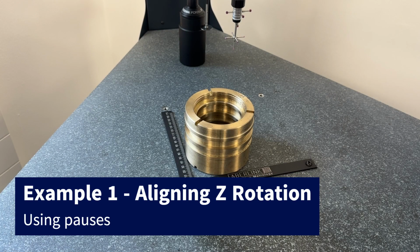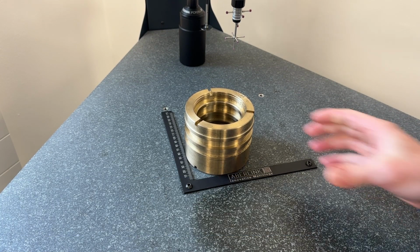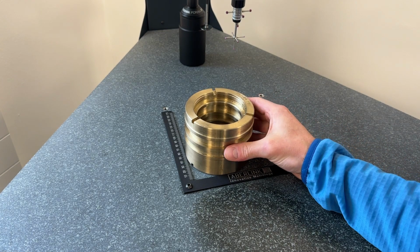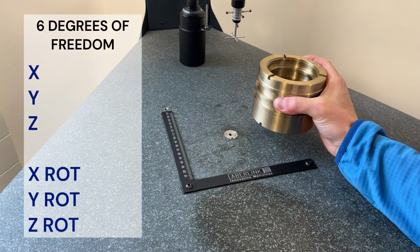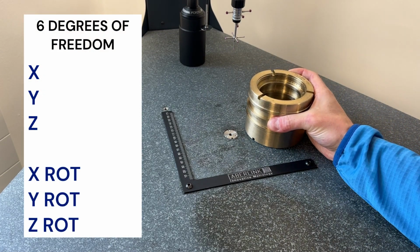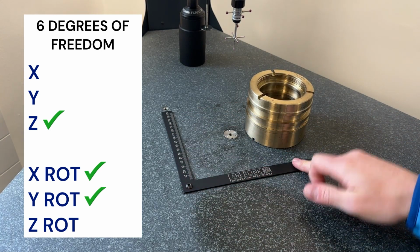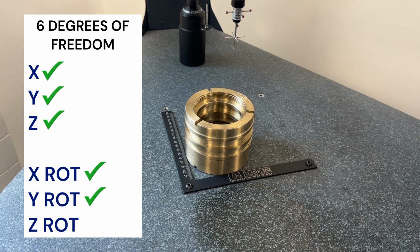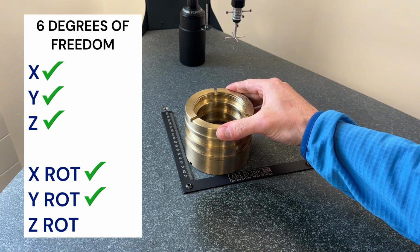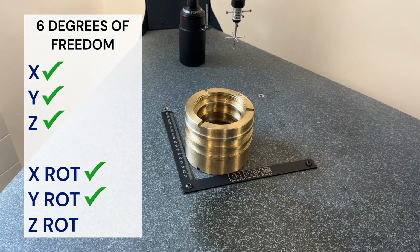So this is example 1, and in this example we're going to utilize pauses and some move wires to help us visually align the Z rotation of the part. You can imagine when we have a part, it's theoretically floating in space. We'll locate it in Z via sitting it on the bed, and this angle bracket can be used easily to locate it in X and Y. The only thing that's then free to move is it's free to spin in the Z, and that is a very tricky thing to fixture.